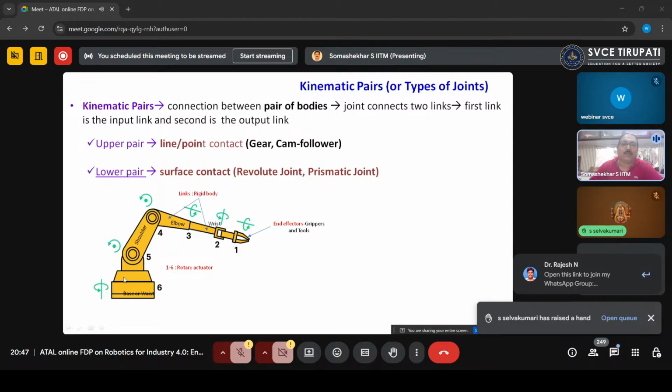This is what we will call the robot. When you are finding out the degree of freedom, you only have to go up to the wrist. Don't attach any end effector. The work volume arrives up to the wrist, moving in different motions depending on the joints you select. The end effector is what we call the grippers or tools.